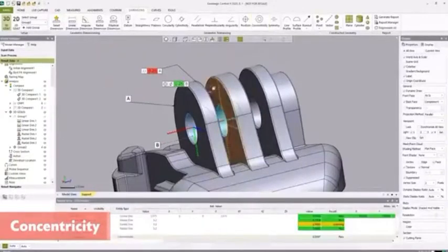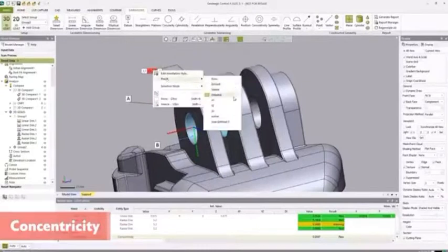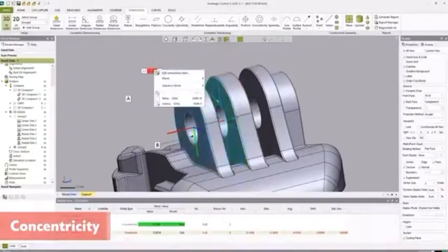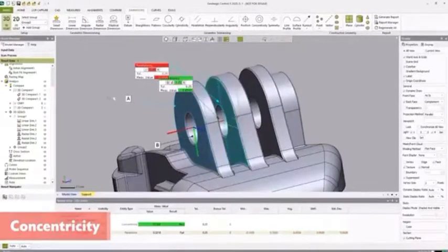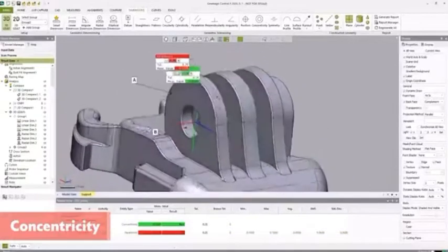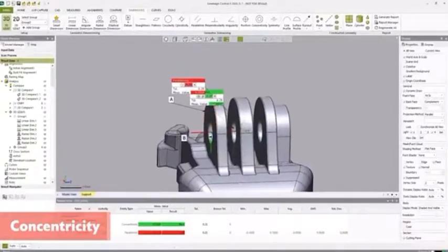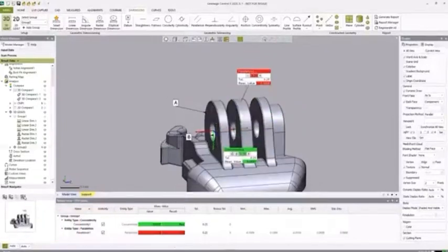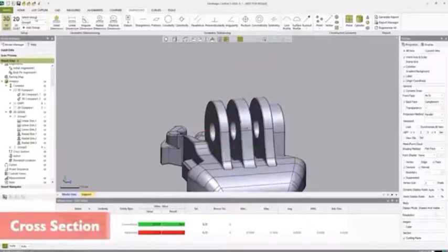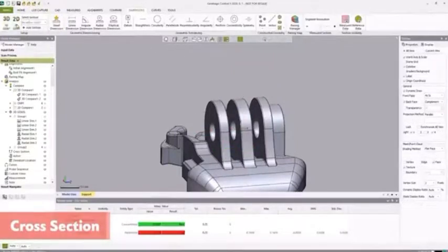And once again, for reporting purposes, orient the part in a way that best depicts critical information. Highlight 3D GD&T in Group 2 in the Model Manager, and in the Result Navigator hit the Reassign Viewpoint, and this will now be generated in the final report. We can now move on to the cross-section tool to create 2D sections from the reference and measured data. The cross-section tool generates 2D section drawings similar to 2D drawings in most CAD packages.